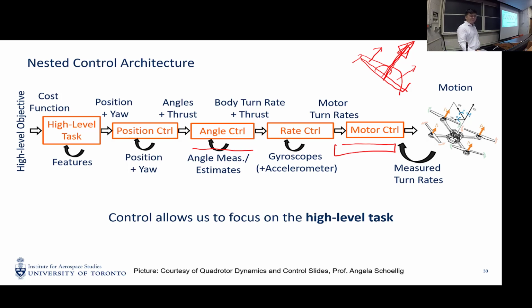And finally, if we can control the total force on the quadrotor, it means that we can control its position. If we want the quadrotor to move sideways, we just tilt the lift a little bit, so it will move sideways and then stop at a given location. This is called the nested control structure of the quadrotor. It's the main control framework used in quadrotors and multi-rotors.